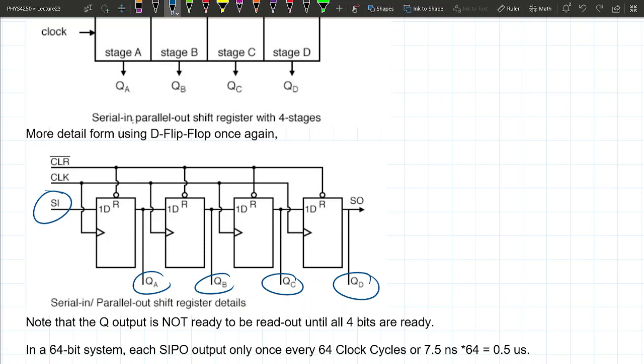It's a very similar design, except, because the shift register works the same way even if you keep going, let's say you had your original shift register out here. You can keep shifting this data on and on. So if you have a serial input here, where you have a single channel of ones and zeros coming in, these ones and zeros can be shifted over one at a time per cycle, and therefore start writing this information onto your RAM or your D flip-flops. The catch is, if you want to write 4 bits, it'll take 4 cycles for you to write that.